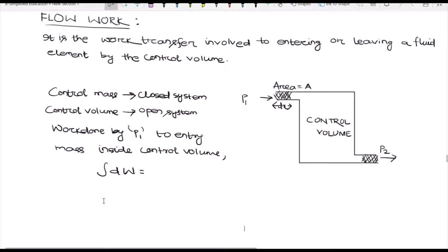In the last lecture we discussed the first law of thermodynamics in detail. Now we will discuss the application of the first law of thermodynamics, that is, steady flow processes. Before coming to the steady flow process, I just want to introduce the flow work. So what is flow work? It is the work transfer involved in entering or leaving a fluid element by the control volume.